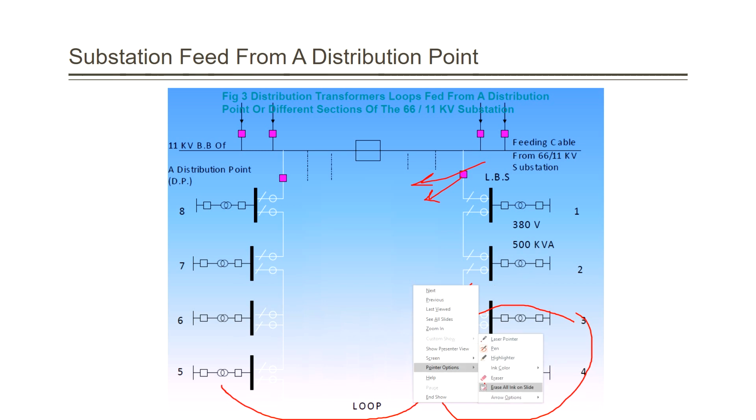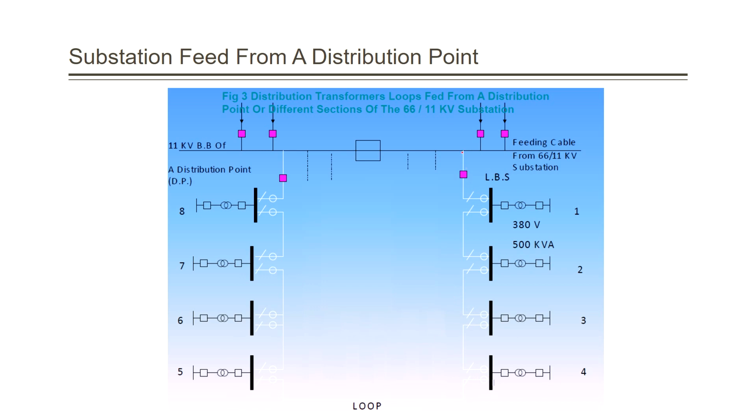So the benefit of it is that in case we have a fault here and we cannot supply power in this direction, then we can supply power to the loads here in this direction. Okay, so the benefit is that if we have a fault here also and we isolated the fault, we disconnected this switch and this one after the action of the circuit breaker. So we provide power from this direction to number 2 and provide power from here to number 3, and between them here is isolated. Okay, so that is what's called a loop.